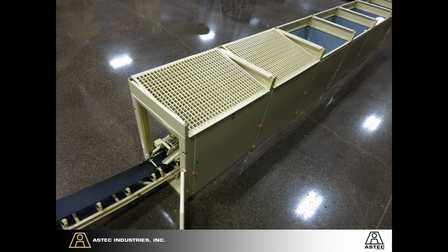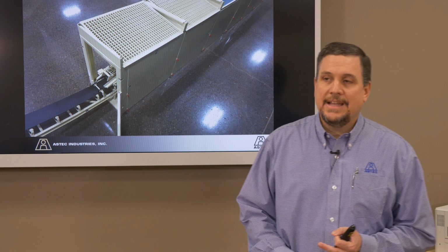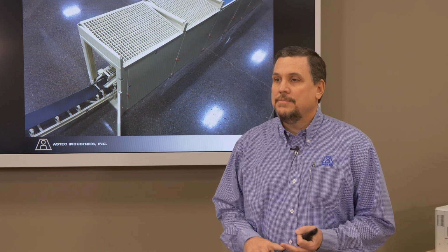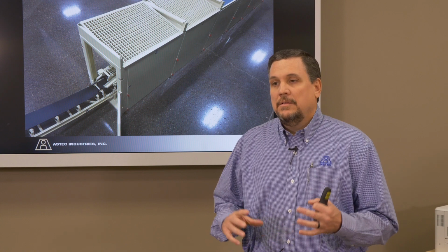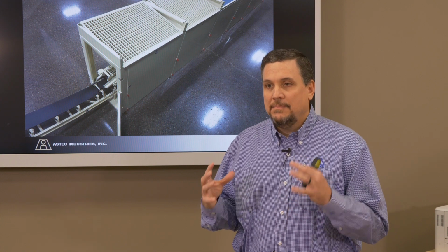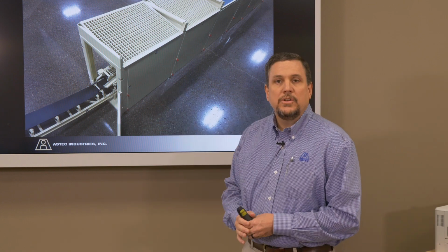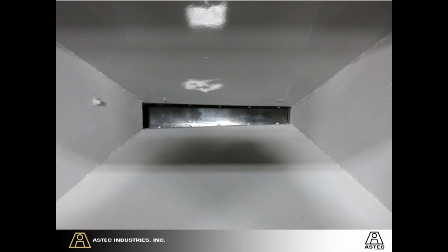If you get a top view of the coal feed bins, this is a grizzly that you see on top of this. Some people ask, what's a grizzly for? Well, a grizzly is to keep all of the debris larger than the specified material that needs to be in that bin. You take sand, things like that are very fine. That's where you see your grizzlies at. The reason that you see grizzlies is because a lot of times roots, debris, sand that has congealed together and made a large ball, you do not want that type of material to fall down into the bin, and we'll talk about that too as we move forward.